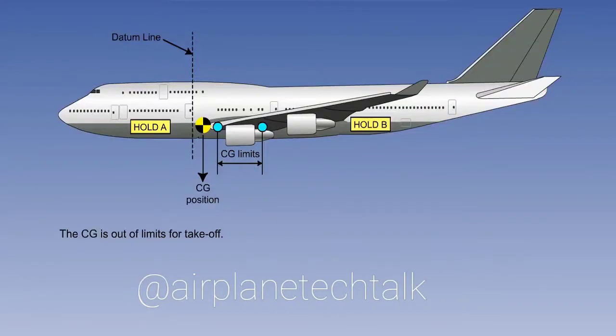In this lesson, we will see that there is an alternative method of bringing an out-of-limit centre of gravity into limits. This time, mass will be added to or removed from the aeroplane in order to correct the centre of gravity. The adding or removing of mass from the aeroplane can take the form of either cargo or passengers, but sometimes operators will use mass called ballast, which is a mass that stands alone.